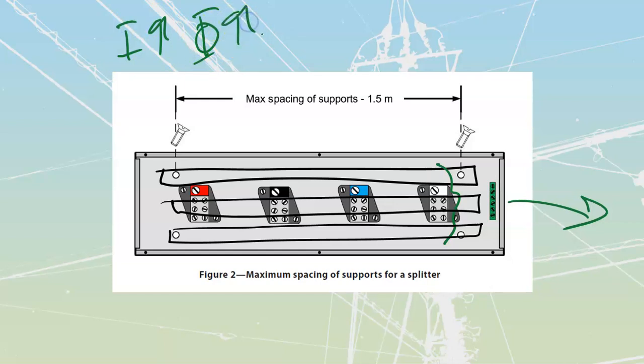And so our flux is going to go up, and since our magnetic flux goes up, that means that we're going to have massive magnetic strains on both our splitter and on the mounting on the wall itself. Because the actual buses, particularly in the bus ones, are usually going to be mounted down in a number of places across the splitter, it's then just up to us to make sure that we are mounting the splitter box itself to the wall so that it's not going to be able to torque or twist out.